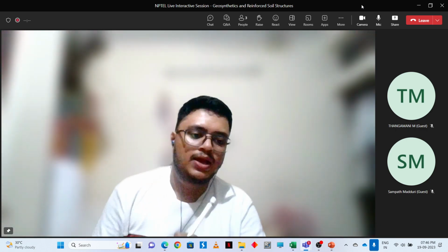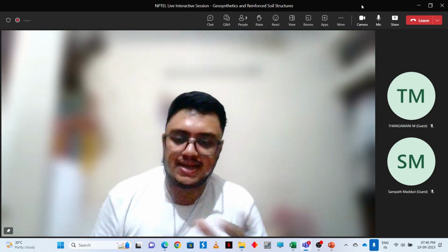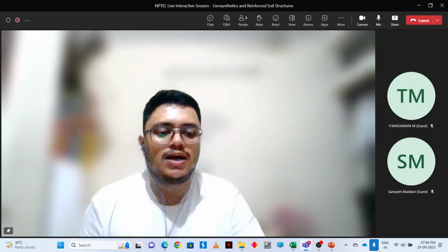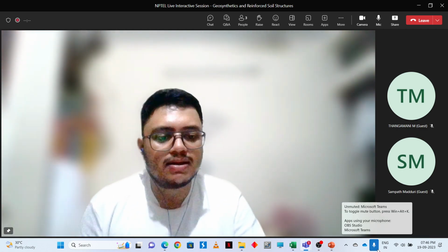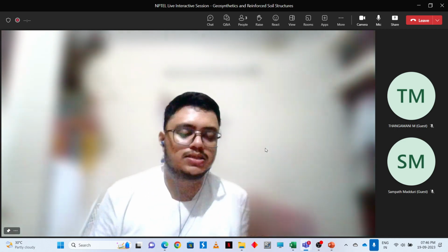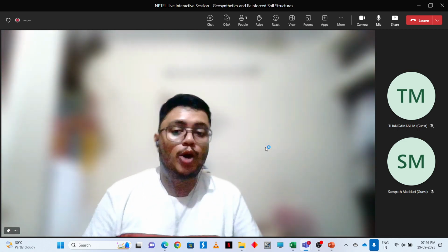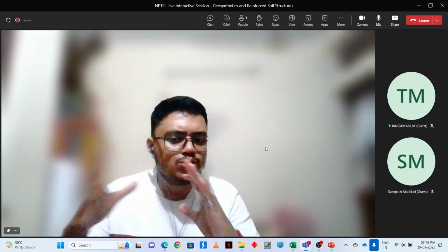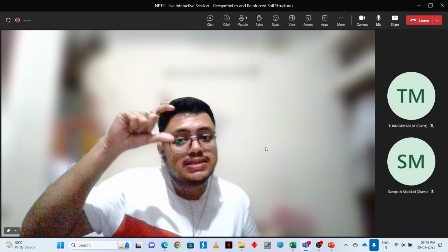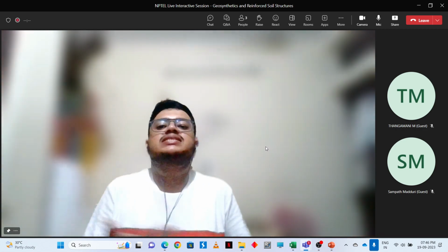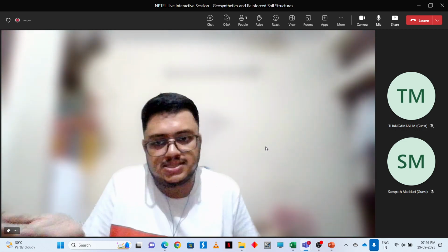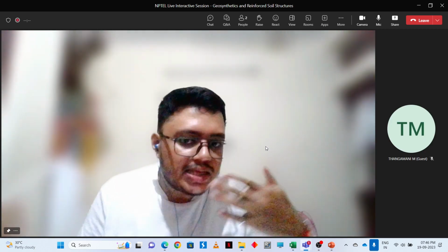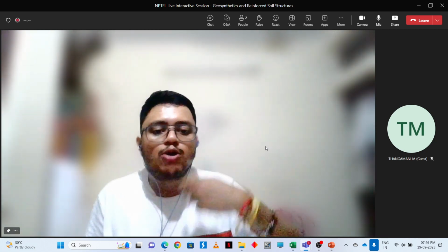actually you need to do some trial and error, and by trial and error you need to get your optimum width and optimum number of reinforcement layers. The spacing also, we just assumed a spacing of 0.5 meter in our case. So everything is up to you. You need to use trial and error to optimize your design.